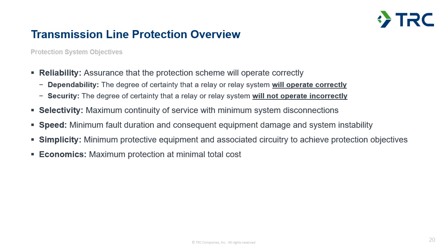If you're not waiting long enough to make an informed decision, maybe you will misoperate for something that you're not supposed to. Generally, for transmission line protection, we're looking at clearing most faults in under a few electrical cycles as far as the detection of the fault. And we'd use a mix of instantaneous protection at either end.